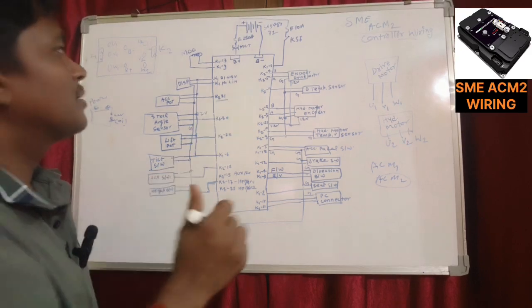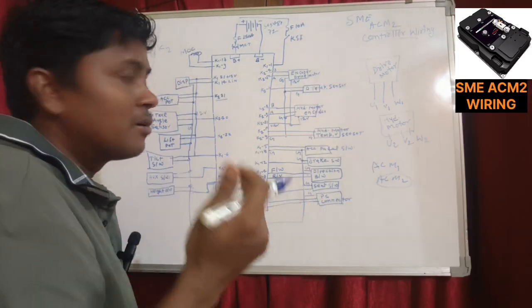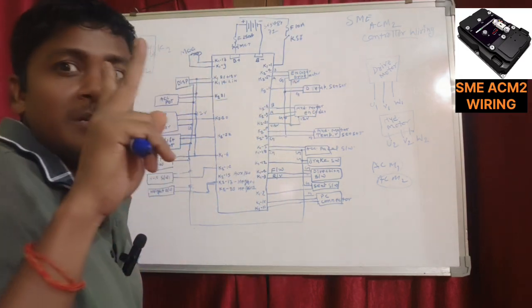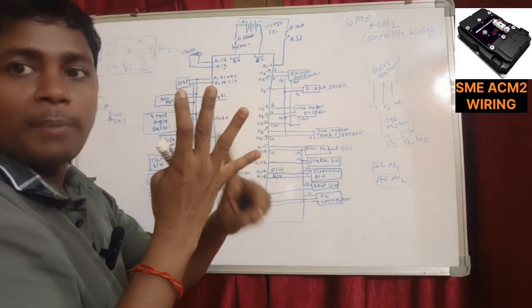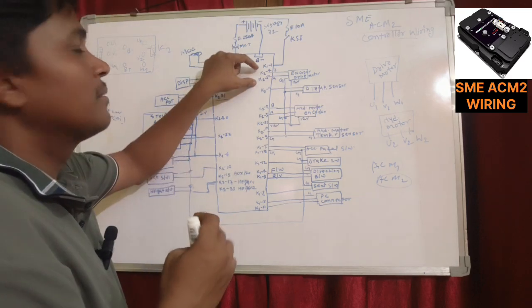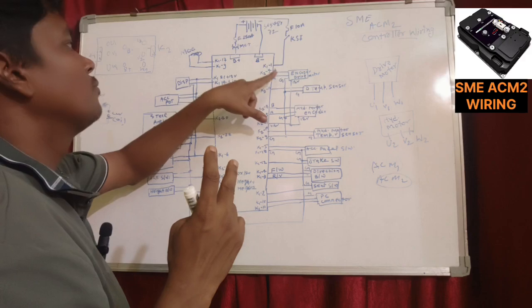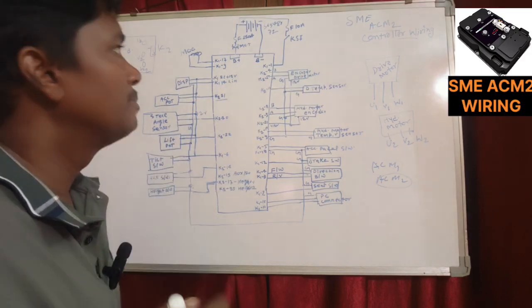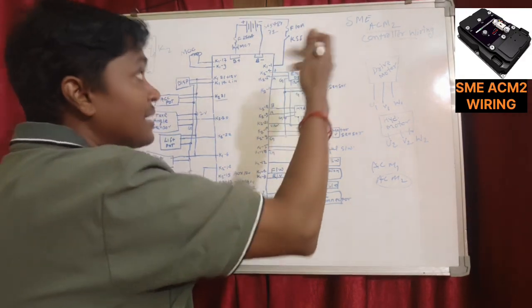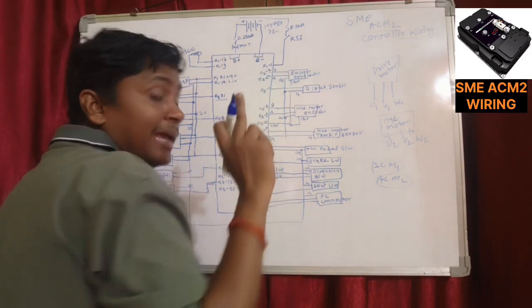See, it is required 4 points because the encoder is required to operate on 12 volt. It will require 12 volt, which will be 2 points: one for plus 12 volt, another for ground, and another 2 points which is a 2 channel encoder. Then K4, K24 and K25 will be connected with the encoder, the drive motor encoder.